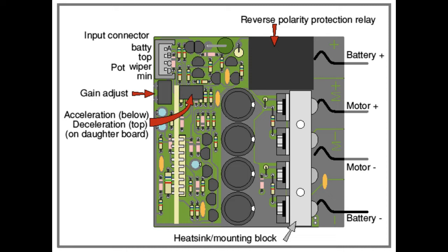However, it didn't work well at currents in the region of 10 amps, so for the loco I set it to 20 amps but used the external circuit I described to cut in earlier. This is where having the circuit diagram helped.